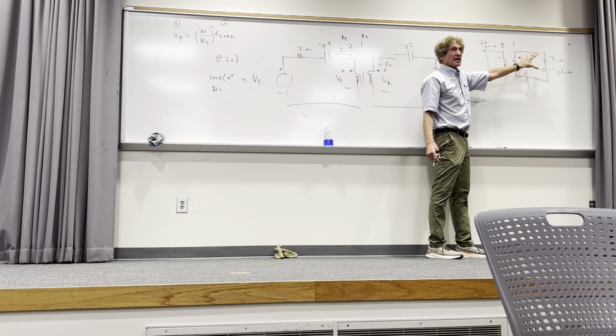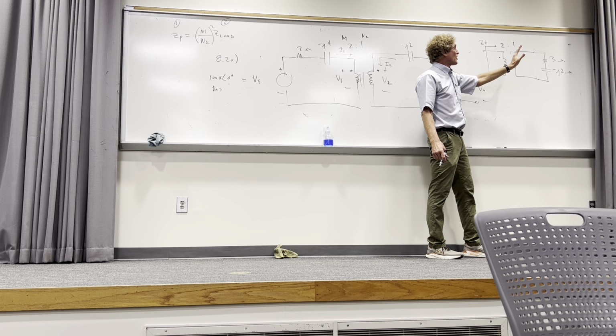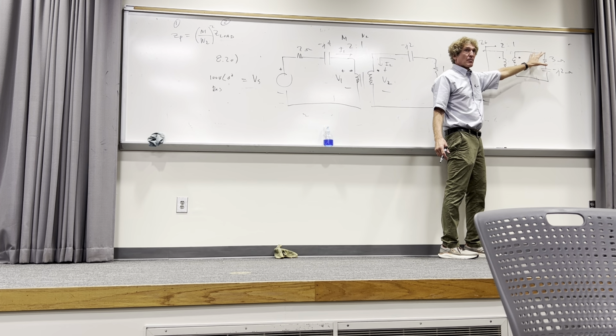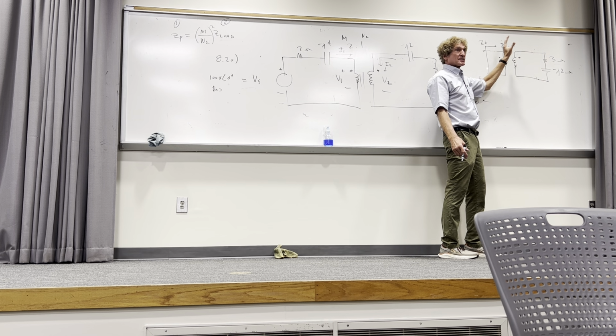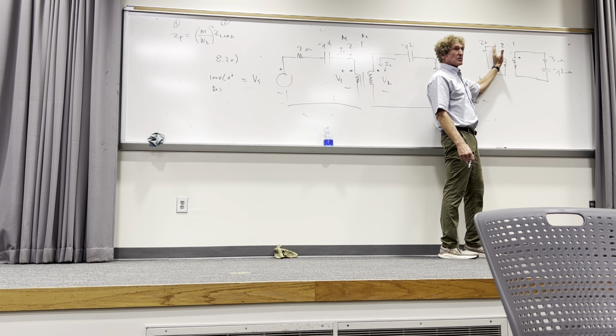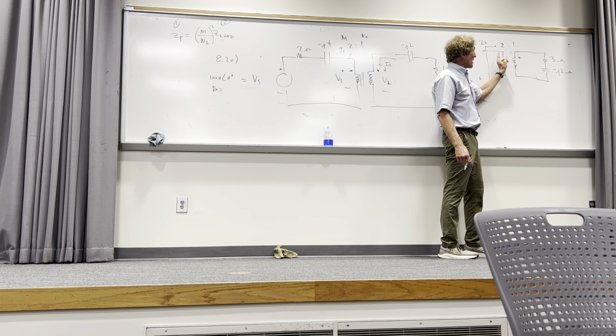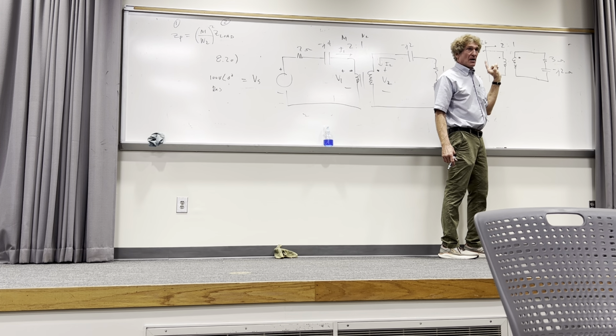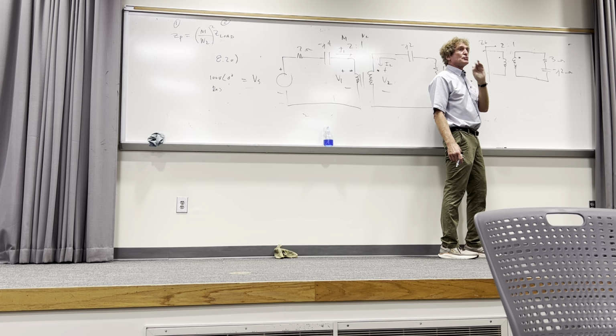And here's what you think. If you go from a side of a transformer that has less turns to a side with more turns, like in this case, the impedance is going to go up by the square of the turns ratio. In other words, this impedance here will be multiplied by 2 squared, or 4.